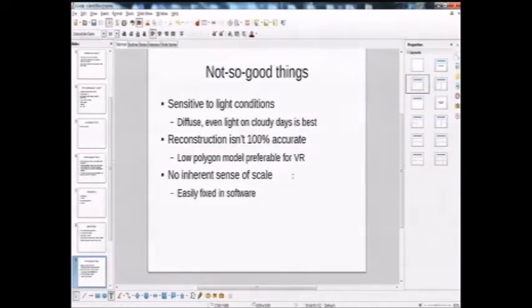That's something else to consider, is all we're doing here is manipulating a three-dimensional matrix of several million elements. That's why we're using something like Meshlab to treat this in a mathematical sense, because 3D scanning, 3D printing, 3D CAD, all of these things are very dependent on having clean data. Now, the easiest way to visualize the most basic file format for 3D scanning results, for an STL file or an OBJ file or a PLY file, the most basic form of any of those files is 3 dots in Cartesian space, like on an XYZ plane.